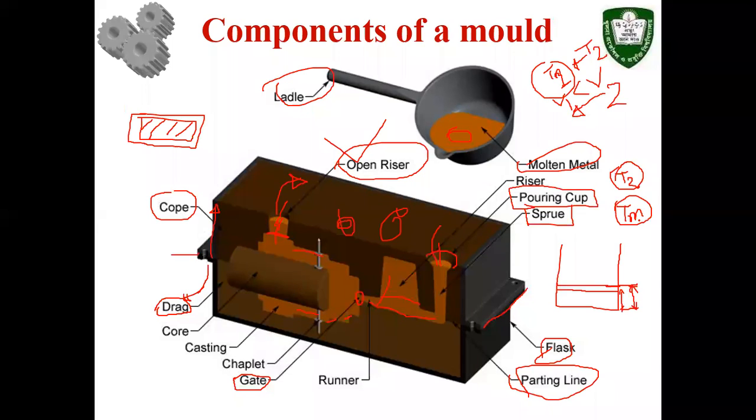Yes, sir. And when it goes to the room temperature, TR, the volume will further reduce. That reduction occurs because the material is solid now. Material is solid at the melting point temperature, and when the temperature decreases to the room temperature, the volume will further decrease, right? So this will be the final volume at room temperature.